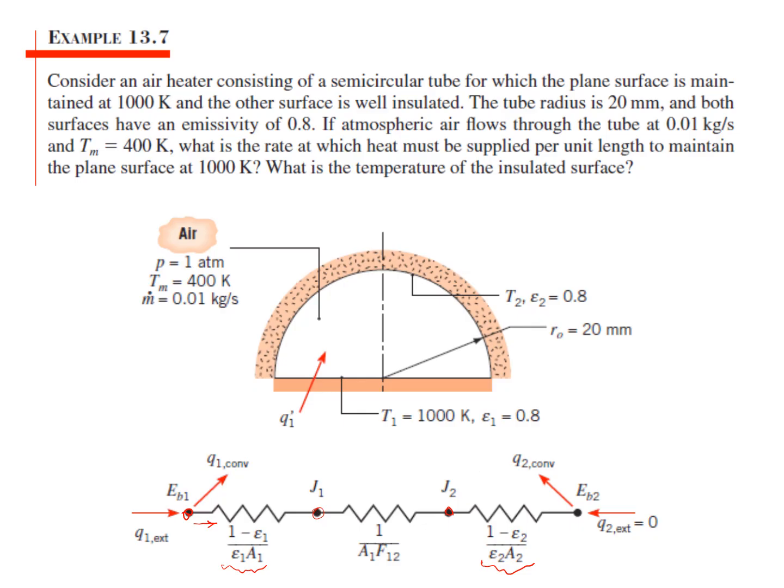Now I want to see what happens here. On EB1, which is my heater surface, I get some heat input externally. I'm using whatever electrical power, whatever I'm using in order to provide heat on surface 1. That's my heater surface. And then I know that some of that goes towards surface 2 by radiation, and some of that is going to be convected. As we said in the multi-mode slide, we are going to put that heat on this EB node. Anything after that, the radiosity nodes, are just for the radiation from one surface to another. So now I'm putting this convection here.